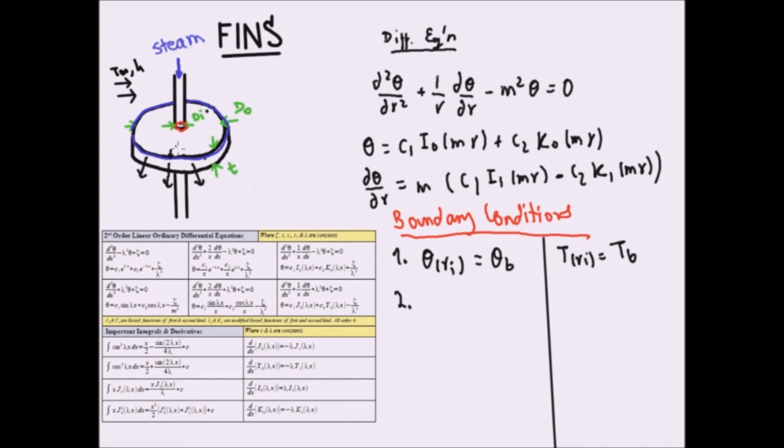So I guess this is conduction, and this would be convection. At this point, conduction and convection are equal, so we can express it as conduction equals convection. Notice that this is the real boundary condition. However, it actually complicates the problem a great deal, and you'll see why.